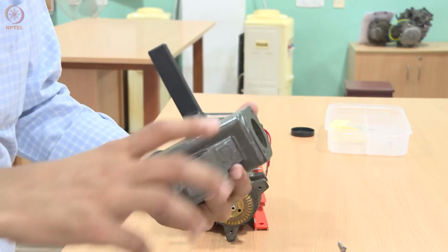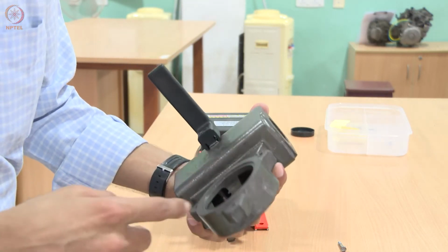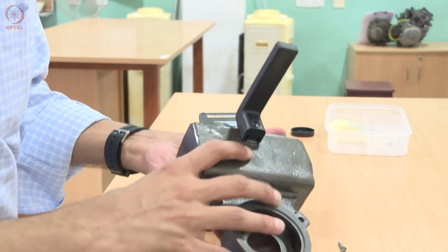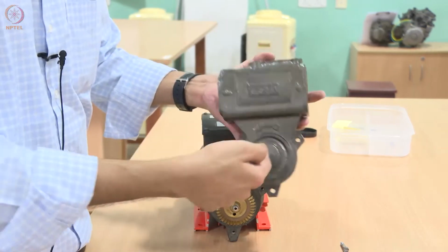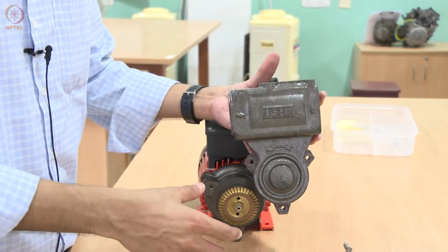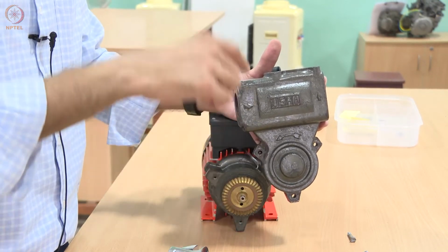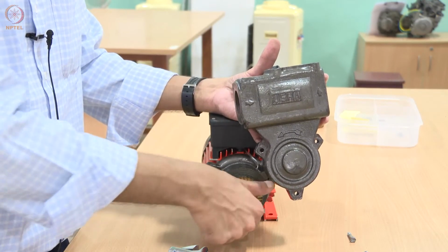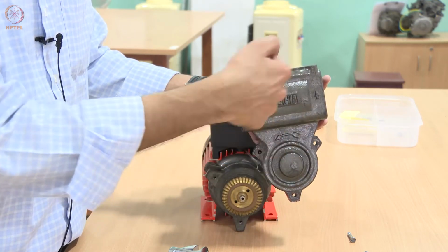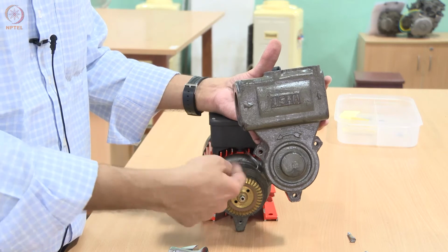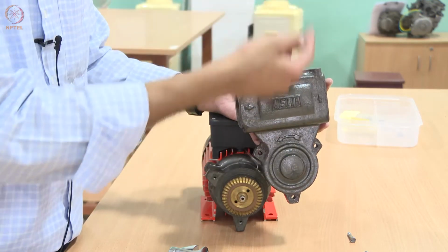Not strictly tangential, but it's almost tangential. So the feature of this design is, by continuously circulating the water, little by little the pump will evacuate the air that is there in the suction line. After you run the pump for maybe a minute or so, the water will keep circulating and slowly it will suck out the air, and then water, because it is dense enough, will keep falling. So water will not be discharged initially.